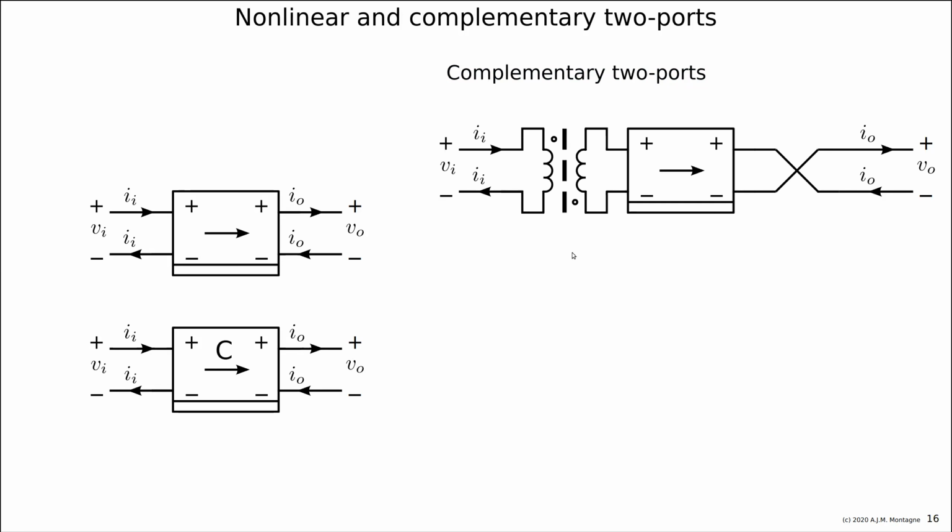So what you basically do is you switch the sign with respect to the nonlinearity of it. The sign of the signal is going to be in the other direction relative to the orientation of the nonlinearity, compared to the normal device. So if the upper device on the left is my normal device, then on the right I have made a swap at the input and a swap at the output of the signal with respect to the nonlinear VI curves at the input and at the output. At one place, I have swapped it with a transformer, which also creates isolation. And at the other point, I just swapped the terminals.